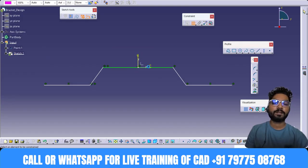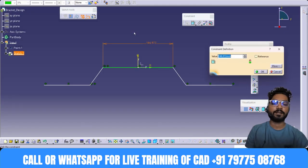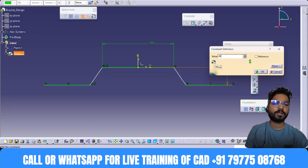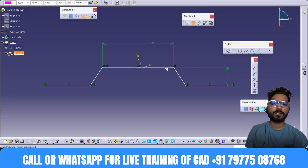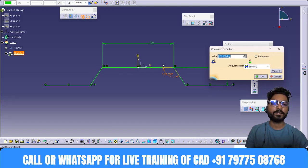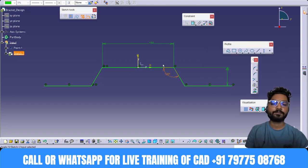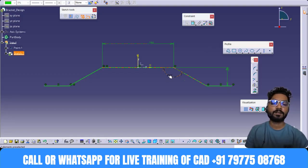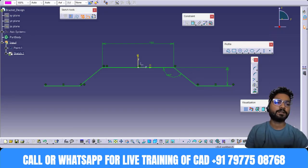After that we'll give the dimensions. This I'll maintain around 150, then you can give this dimension. This dimension will keep 40, and then you can give this angle also. The sketch we are going to create with fully parametric constraints. So this will give 120 degrees or 130, 150 will keep. We are generating a concept here, so we'll see what is suitable for our creation. Now I want to exit, so right click, workbench, exit workbench.